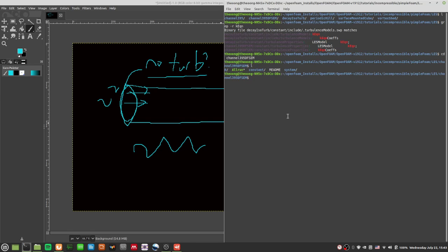You will use this thing called the DFSEM, the Divergence-Free turbulence generator or something like that. I can't remember exactly what it is, but anyway, this is one of the boundary conditions, and you will see here there are 4 fields. One is k, one is nuT, one is p, and one is U.